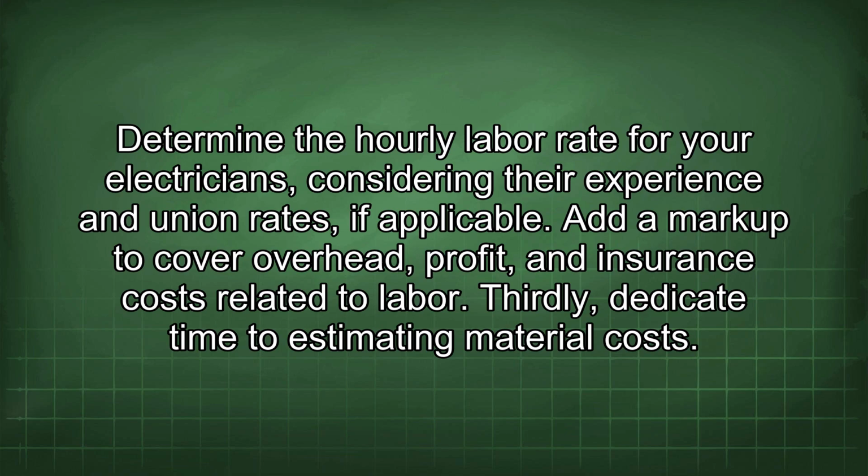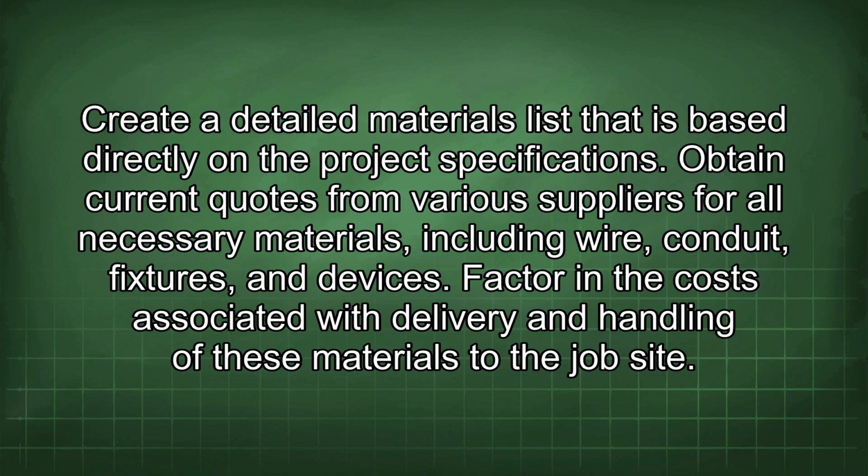Thirdly, dedicate time to estimating material costs. Create a detailed materials list that is based directly on the project specifications. Obtain current quotes from various suppliers for all necessary materials, including wire, conduit, fixtures, and devices. Factor in the cost associated with delivery and handling of these materials to the job site.